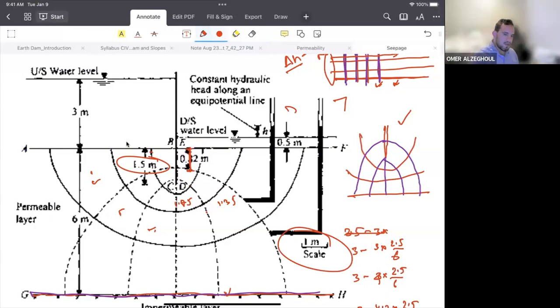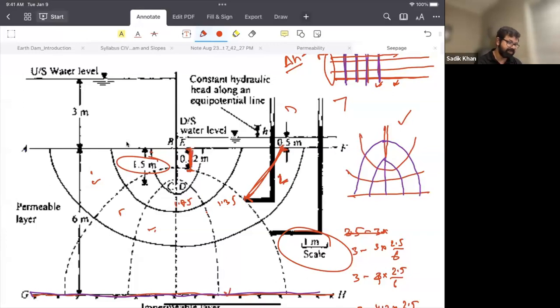That's the distance between the last drop and the surface, right? Yeah, the exit gradient at the first one, you know, where the water is exiting, the first one, not here. But it should be the same thing. The exit gradient here, no, it's not going to be the same thing. Here the pressure drops. Because here your L is higher, you know. Your head difference is same, but L is higher. But in this one, your L is lower. So exit gradient you need to calculate for which one you have the lowest L.